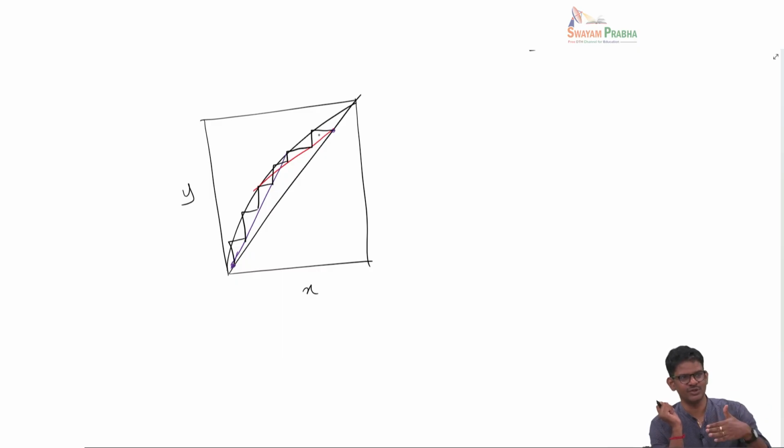Depending upon the reflux ratio, the slope will change, and the intersection point between these two lines will also change. So there are a lot of interesting questions to be answered. How do I choose the reflux ratio? It has a range from 0 to infinity. What is the optimal reflux ratio to use? Once you do that, the operating line slope will be different. Where do they cut? And what is the quality of the feed? Is the feed always a liquid, or always a vapor, or a mixture of vapor and liquid? How do we deal with that? And how do we find the feed location? Those are interesting questions we have to pose.